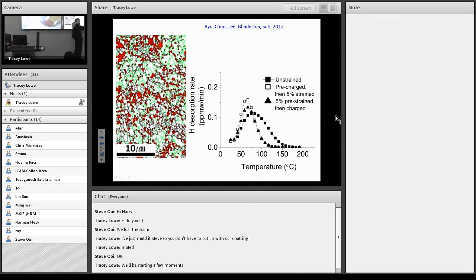This is the specimen which has not been strained. And these are specimens which have been strained so that the austenite in this particular steel has decomposed into martensite. And you can see that suddenly the hydrogen becomes diffusible. The hydrogen that was trapped in austenite will become diffusible.